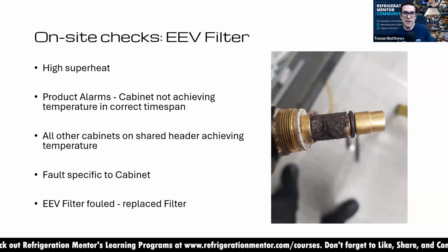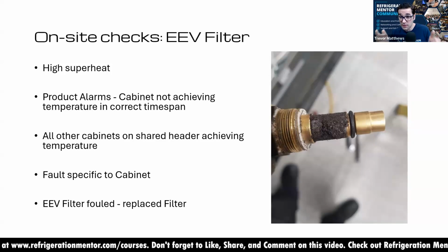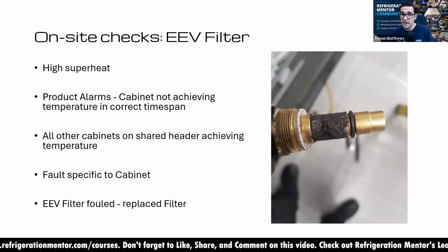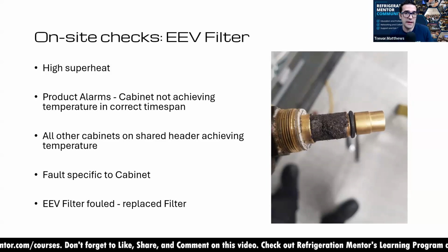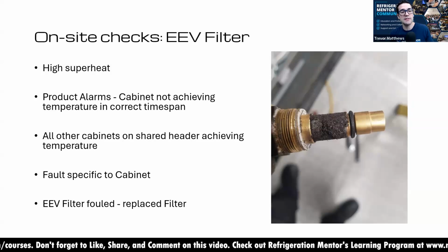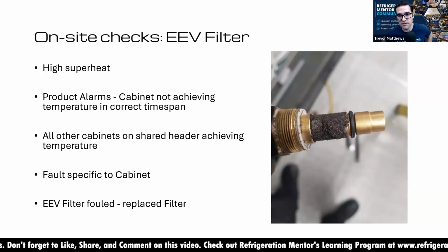But when he told me that, all the trees and all the grass is dead around where that relief is. So you guys got to think about that. Yes, the CO2 is not a problem, but if you've got POE flying out with it, because we know that refrigerant going throughout the system has POE in all of it. So just think about that next time you're relieving CO2 out of a system.